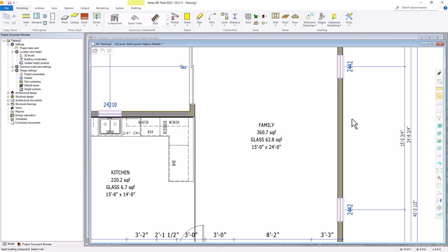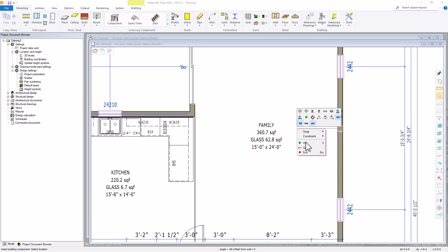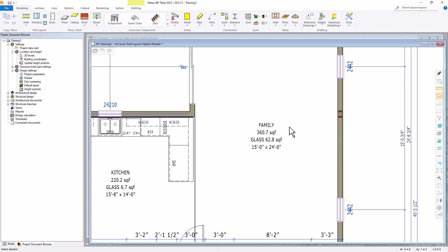Next, click on the right exterior wall. With the beam pocket macro linked to the wall, we need to set the location of the beam pocket. Select the wall center line of the exterior wall at the kitchen. This will line up the beam pocket with the center of the wall. To exit the command, select the Escape key or right-click and select Exit. As you can see, we have a beam pocket in the wall, which is in line with the kitchen exterior wall, which is also in line with the drop beam.